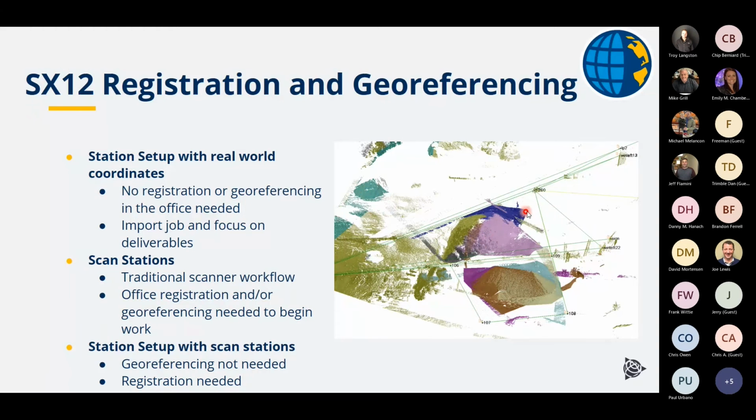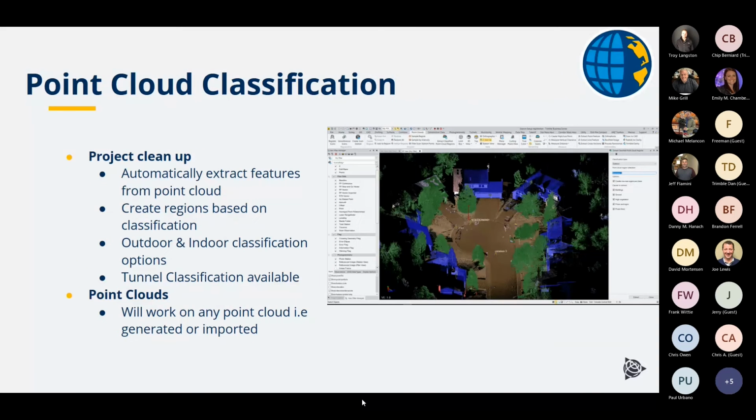But what I wanted to say is, let's say these were blue vectors, which is very common, is people will just go out here, measure with the RTK, backside into those RTK shots, and then perform the scans. So the interoperability between total station and GPS is very easy to achieve if you're already a Trimble Access user or if you're new to Trimble Access.